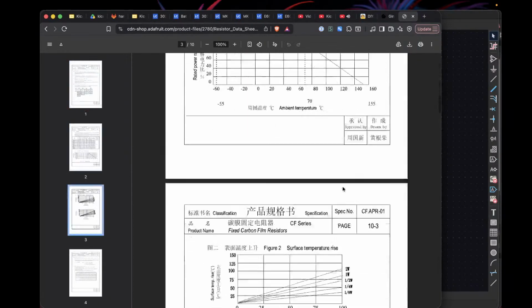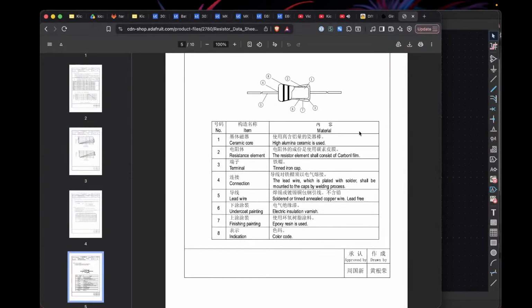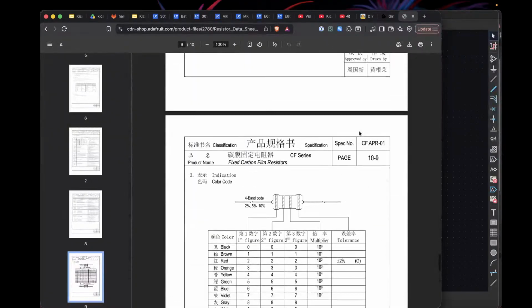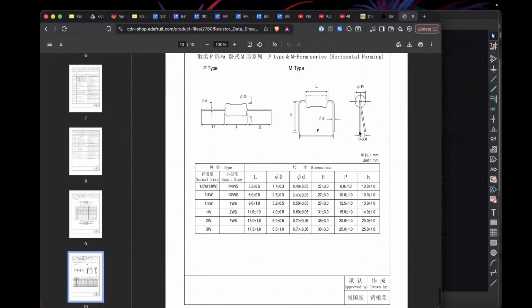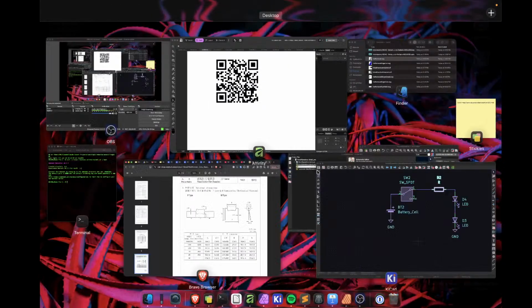And here, there's all this stuff in the data sheet, but then it will usually show, I hope this one shows it, the lengths and the width and the height of everything. And so from this, we know that this pitch will define what the pin spacing is supposed to be for it. And so we would go through and pick out the dimensions like that.